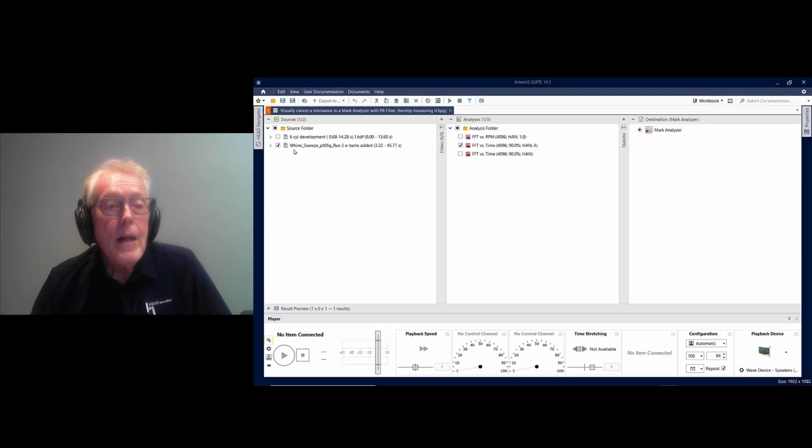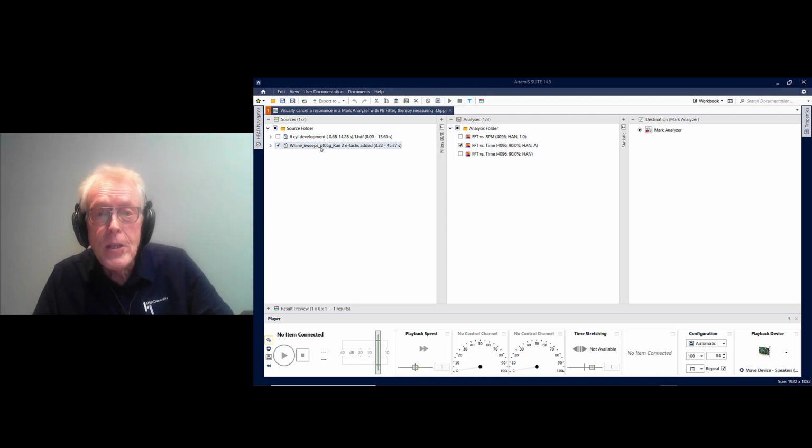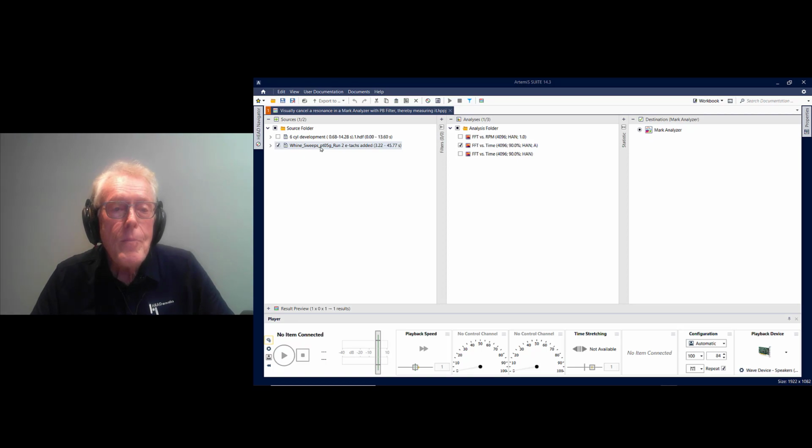Here is an electric vehicle, all-wheel drive, a passenger car, that has a rather pronounced tire resonance, and we would like to evaluate perceptually what happens if we cancel the resonance. That's one point. The other point is that by using our eyes and a spectrogram versus time, like an FFT versus time or RPM, we can visually cancel the resonance and have it be exactly the same as the information on either side of it in frequency, thereby also being able to measure it to find out what is the bandwidth and what is the magnitude.